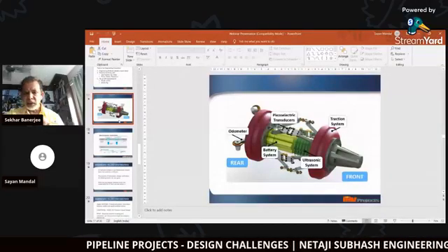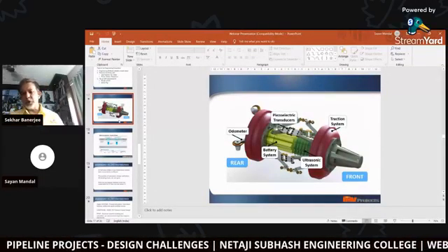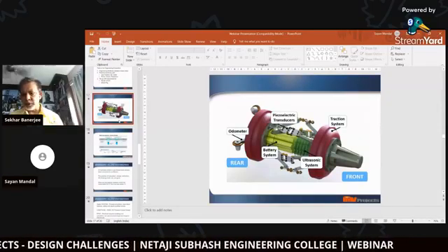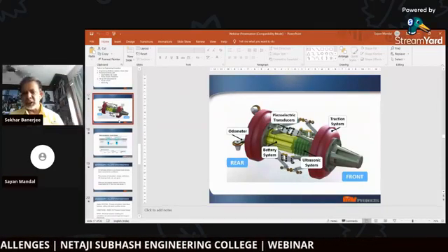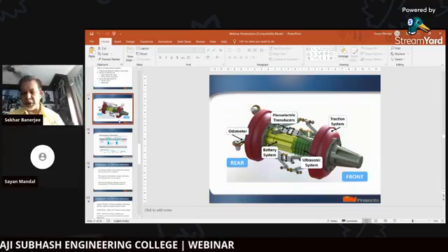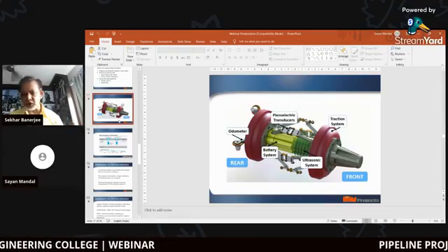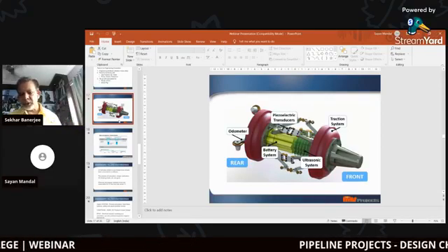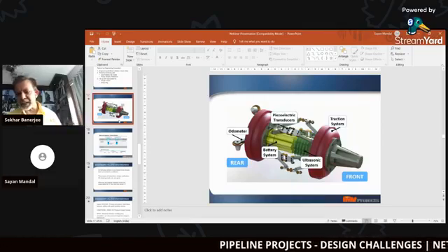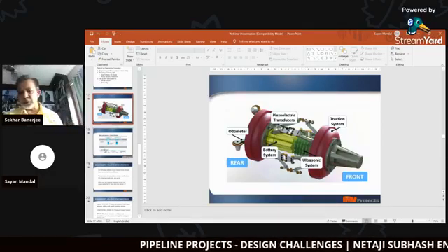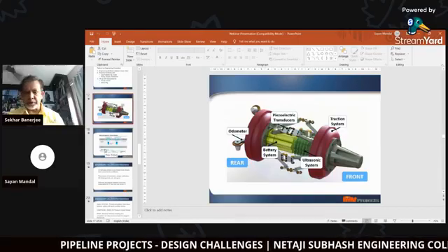is inserted into the pipe. How? When you're pumping the fluid, we just stop it momentarily. Then we push one of these pieces of equipment into the pipe. There's a small hole to do this job. And then we start pumping again. The fluid at the back pushes it to the front, and it keeps on rolling.